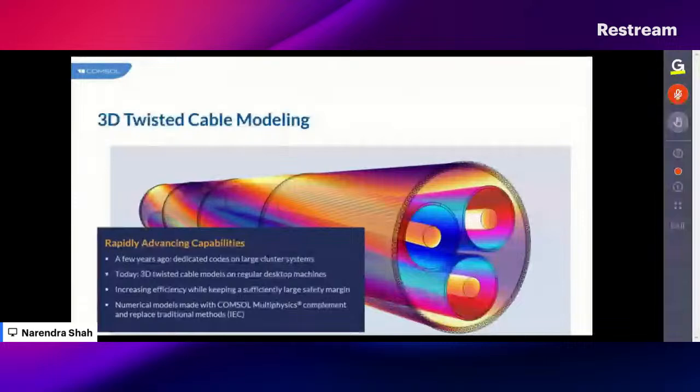That would be computationally very prohibitive. So in that case, we need to come up with some sort of electromagnetic or numerical approximation features. Within COMSOL, we have these periodicity features that are available in the form of twisted periodicity. We'll see some of these features in the demonstration as well, and of course, you can also straight away refer to them from the COMSOL website as well.